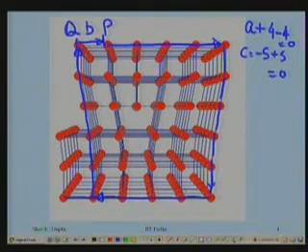The reference is what? Depending upon what is my reference. If I have taken my bottom as a reference, I have found out displacement on top, that's correct. If you take top as the reference, find out displacement at the bottom, you will get the opposite. So we settle this ambiguity once and for all by saying that the Burgers circuit is drawn using a right hand screw notation.